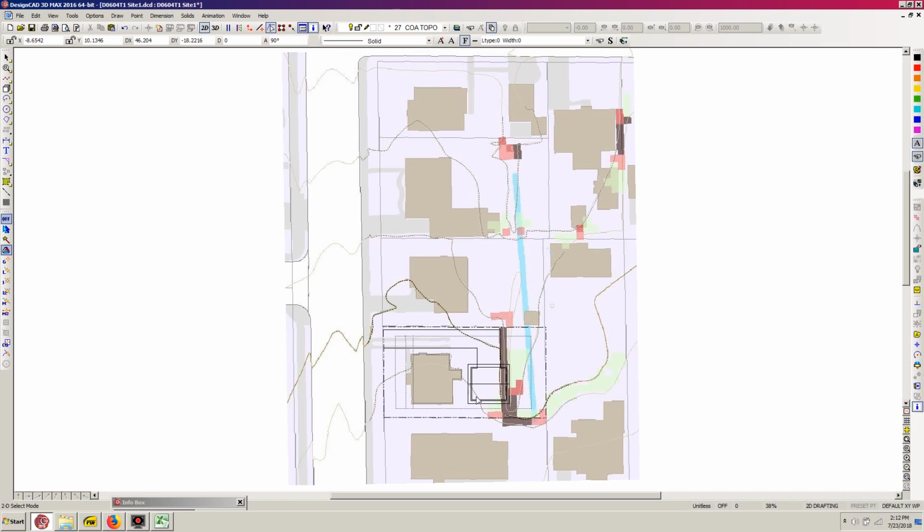We have our garage location right here, so we can easily measure the eave line, which is probably going to be the highest shade producing point, to the property line to see what our actual existing setbacks are to that north property line. In order to do that, I'm going to need to fill in some information on my solar setback calculations spreadsheet.